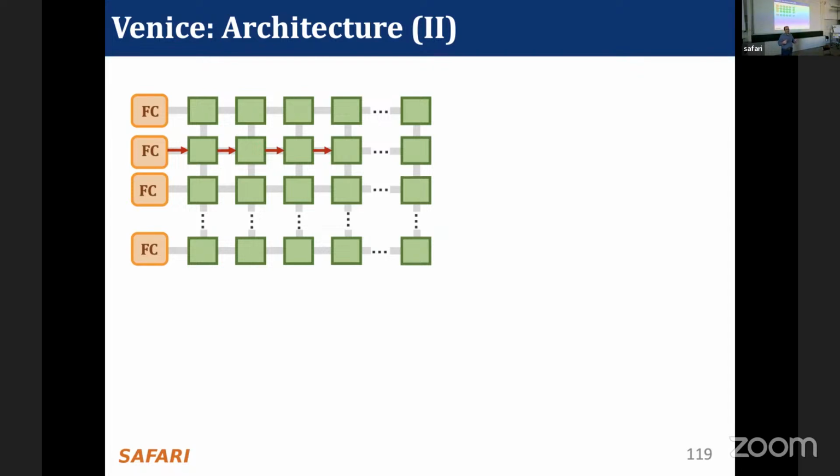We mostly care about whether or not we can reserve a path. That path can be a minimal path like this, but sometimes you're already blocked in the network, your network is so crowded, and you really need to find a non-minimal path. That's the reason we are using non-minimal adaptive routing. We intelligently use non-minimal, fully adaptive routing in order to reserve a path as much as possible.